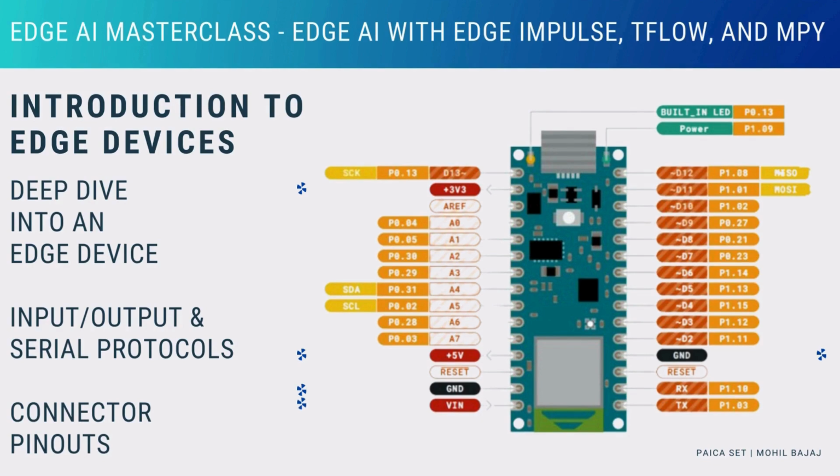V-in, as the name suggests, is an input power pin, which is connected to a higher voltage, like 5 to 10 volts. Note that when the power is supplied to the board with this pin, the USB power is disconnected. Also, always remember to give a voltage amount less than the voltage limit to prevent damage to the edge device.